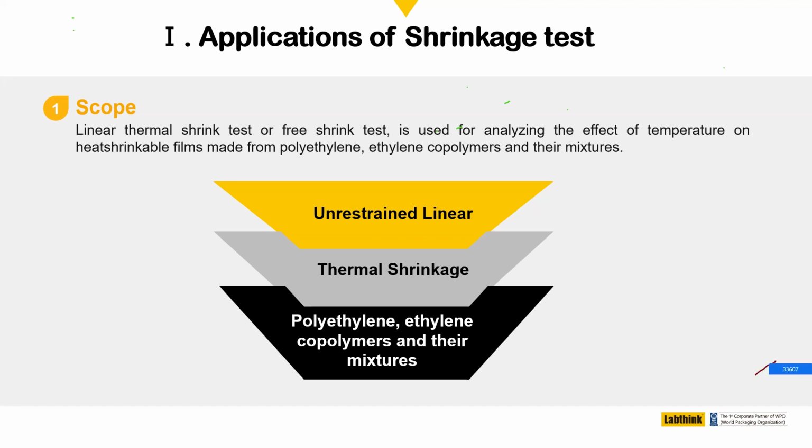Likewise, at the next stage of the process, where the bottles are packed into trays, and then again shrink wrapped, typically with some kind of polyethylene wrap, it's important that the overwrap is not so strong as to crush the bottles, but likewise it cannot be so loose as to permit them to move around very much. So in some cases